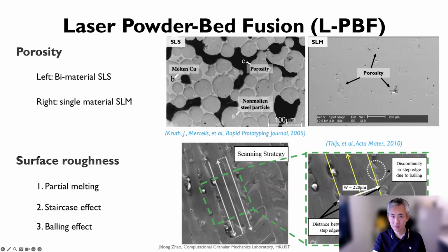Okay, of course, the other thing with these different technologies is that when you do melting, sometimes only some particles partially melt, and some particles are left unmelted here, and this will generate different surface roughness, or the so-called balling effect here. This will affect the performance because sometimes the surface smoothness or roughness is pretty critical for certain needs here.